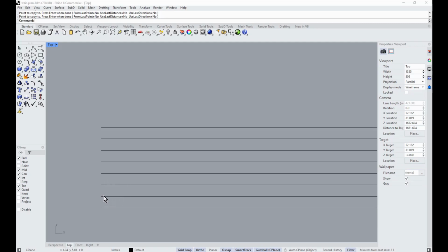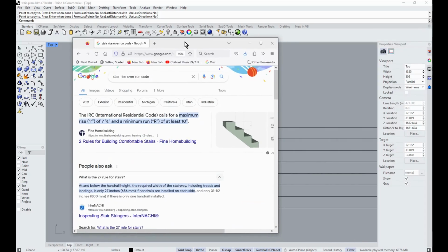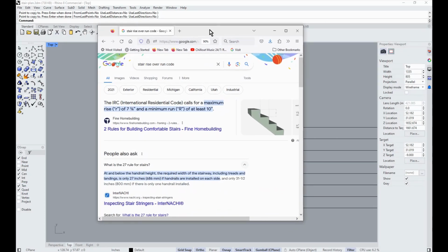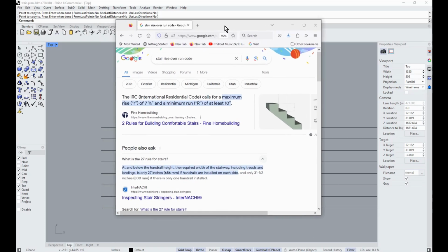Let's just say we want a section of maybe 6 treads. I should mention that a lot of people are trying to pinch square footage on a floor plan, and this is an area not to do that. If you have a 2-story home with a lot of living space upstairs, then this is not an area to pinch square footage. Unfortunately, as you add more treads, it occupies more square footage of your floor plan. That is something to consider, but it's going to create pain for the rest of the house if you have something almost like a ladder. So best to plan accordingly for how many treads you're going to need, if you need landings and so forth.